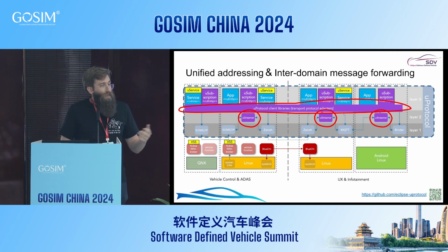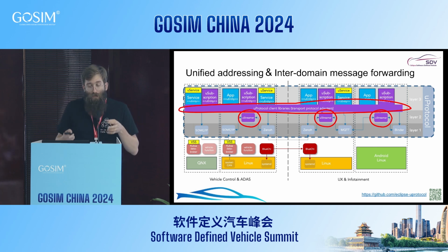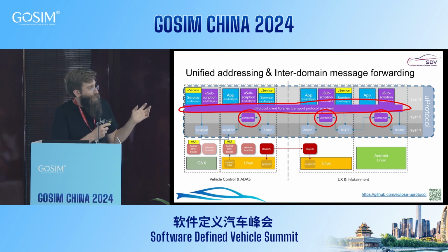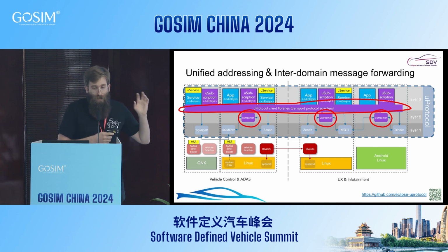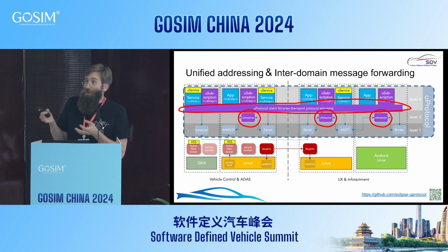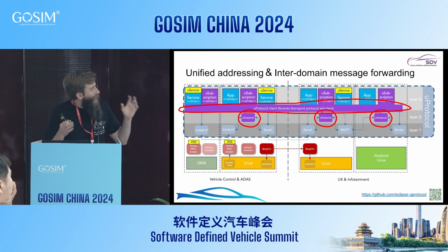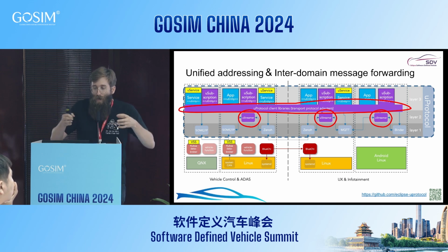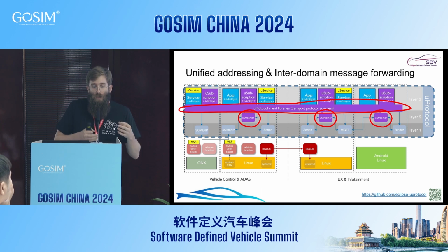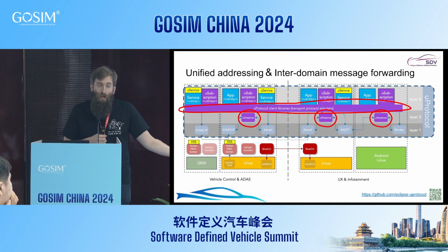Once that's implemented, which one time maybe takes 500 to 1,000 lines of code, those transport implementations can be plugged into other parts of the ecosystem, such as this layer 2 component called the uStreamer. It's the protocol bridging library. Say I'm on this device, where all of my apps maybe speak Zenoh, but I want to communicate down to a brake controller over SOME/IP.